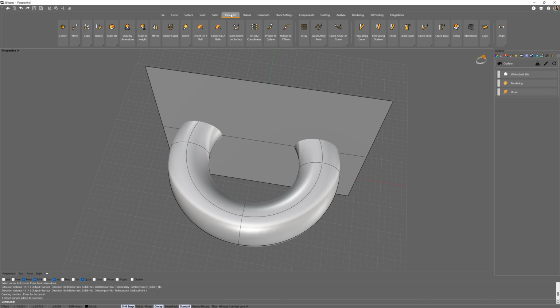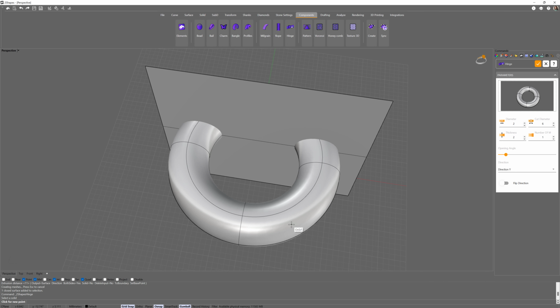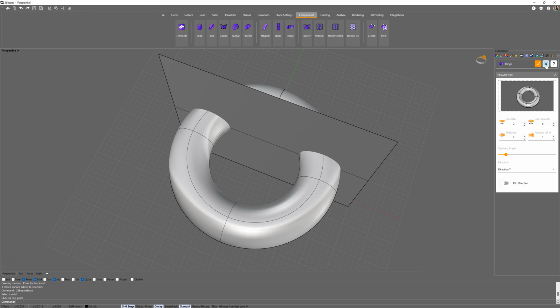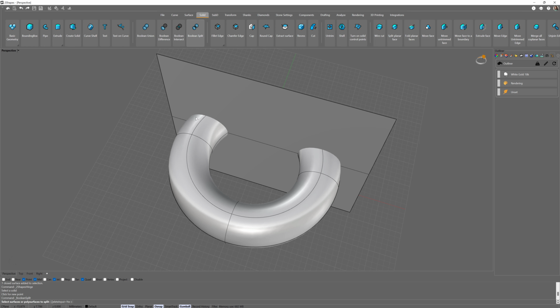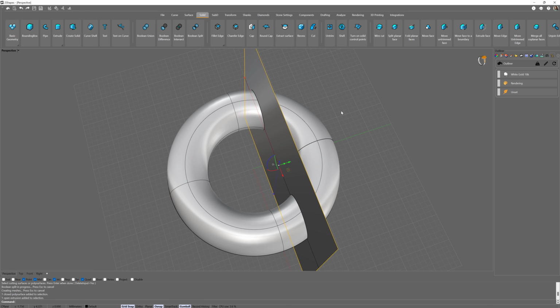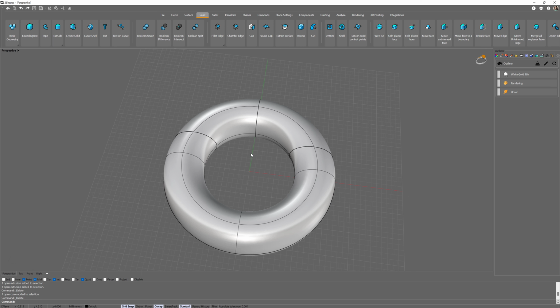Let's create the hinge here. Then we come to components, we click on hinge, we select the torus, and we type a point, for example here. Invalid geometry, I cannot do the boolean. Let's do one thing. We can now come to solid, boolean split, and now we have two solids, splitting where you want.